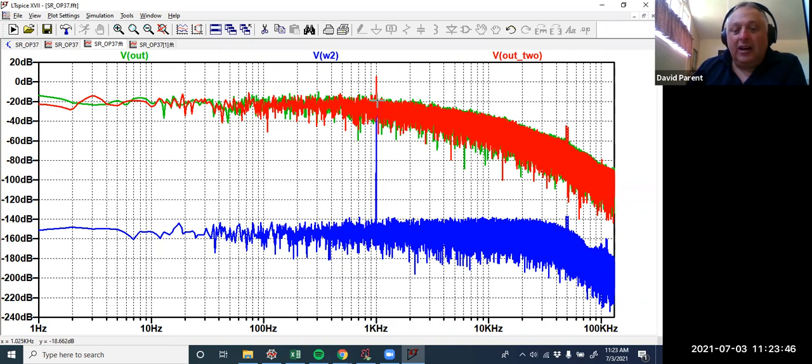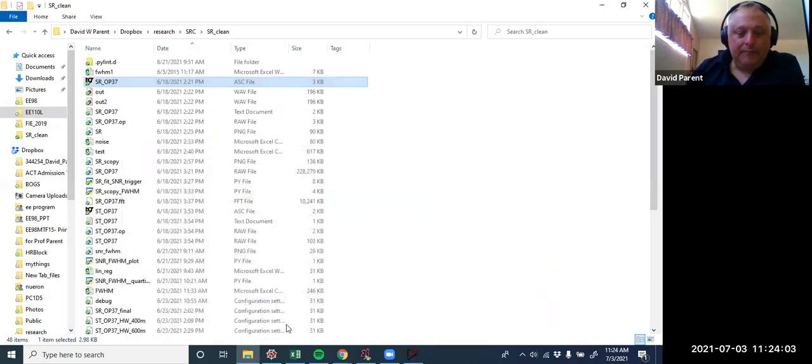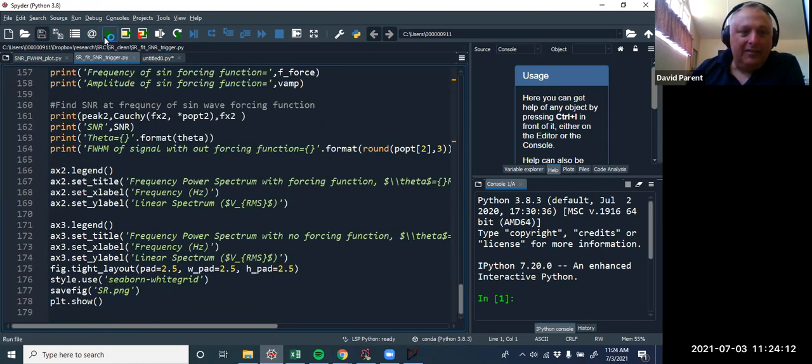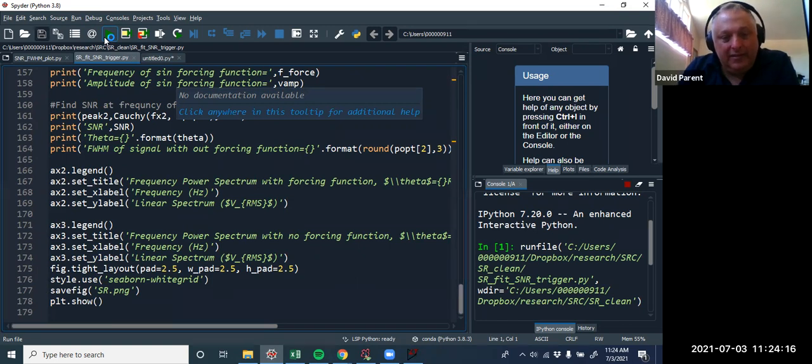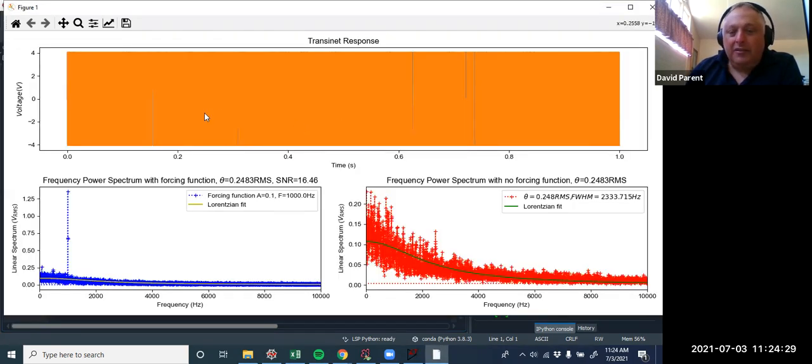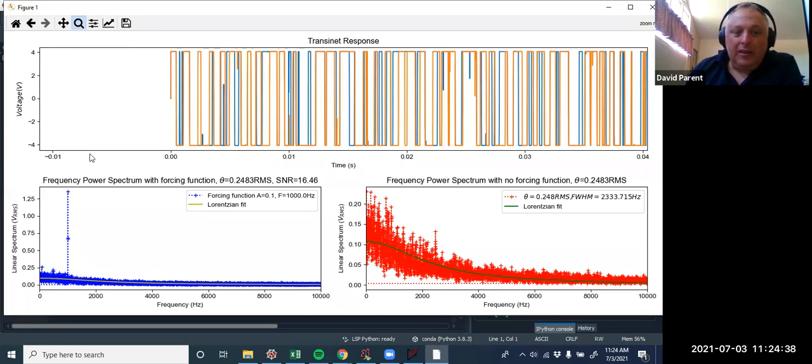But this FFT, what's difficult is that everything's bouncing around. And so we do a power spectral density, which kind of averages everything out, okay? So actually this reads in that data and automatically plots it. Now, this plot isn't particularly useful, except it does tell you that it was switching off and on. If the input noise is too low, the output of the Schmitt trigger won't go high and low. It'll just stay one spot or another, right? But you can tell, right?